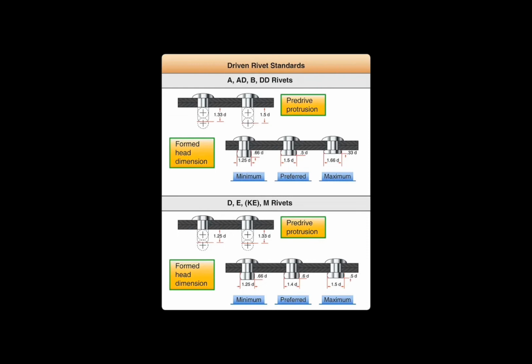What is a joggle? Offset near the edge of a piece of sheet metal. Joggle, offset near the edge of a piece of sheet metal to allow clearance for a sheet or extrusion. What are several methods used in forming sheet metal? Folding, bumping, crimping, shrinking, stretching.